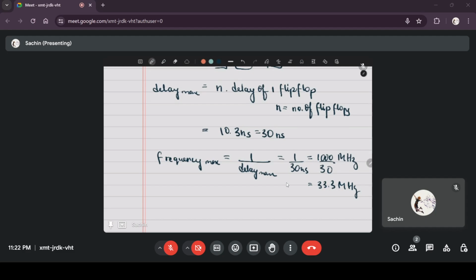So if you take the output at that time instant, if you have some circuitry that is taking the output and measuring it and using it before the entire 30 nanoseconds is up, then it might use the wrong output. It might use the wrong count. So the entire working of any circuit you use, which depends on the counter, is compromised.